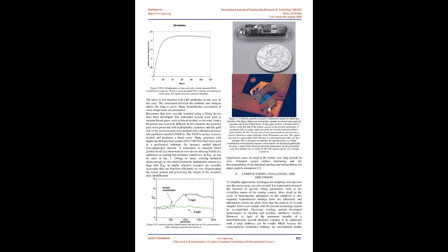The E-beam evaporator first coats the cantilevers with chromium, 2 to 3 nanometers, and gold, 25 to 30 nanometers. The organosilane coatings are often of the form of a monolayer but may be multilayered as the formulation is expanded. Any experiment is planned for practical surfaces. Using several sensors in tandem increases the sensitivity of micro-cantilever array detection. For biomedical applications, such improved reliability is especially important.